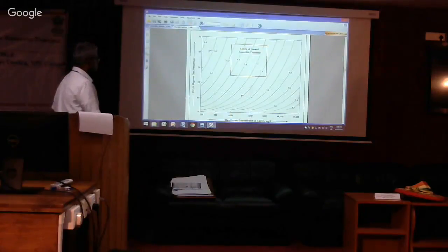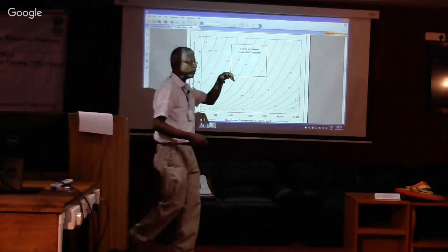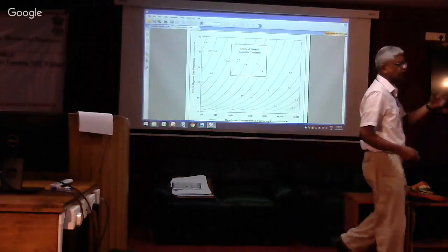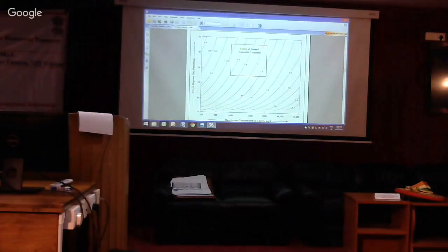What do I mean by stable reactor? You see, carbon dioxide is present in your off gas. So carbon dioxide, of course, has solubility. We know Henry's constant. So the carbon dioxide present in the off gas will come into some equilibrium with the solution. And in this pH, as you can see, if you're looking at alkalinity, it is all bicarbonate alkalinity, right?